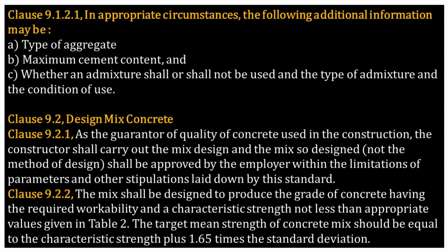Clause 9.2.1, as the guarantor of quality of concrete used in the construction, the constructor shall carry out the mix design, and the mix so designed, not the method of design, shall be approved by the employer within the limitations of parameters and other stipulations laid down by the standard.